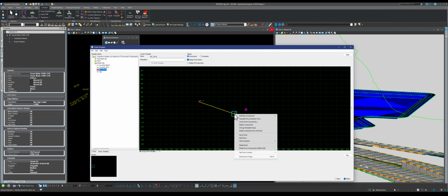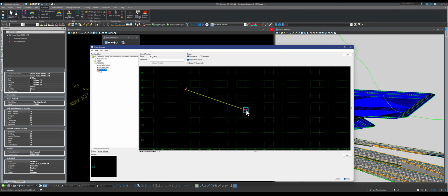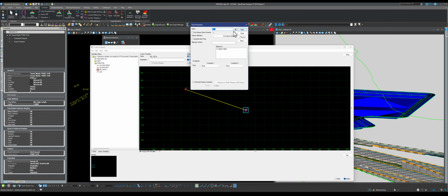The first thing is you come here, change the template origin, because all templates need origin. So this is the origin. So now let's double click on a point. Let's call this, for example, CL, right? Or center line, which is basically the start. And the green one, as you can see by colors, the points, the red one, that's meaning have constraint on them. So all your templates, they are always the typical way. They have one green button and the rest are red, because the reds are connected to this.